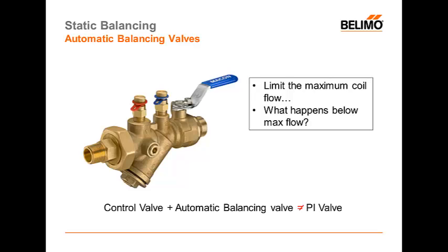One thing that's a very important point about automatic balancing valves. If you take an automatic balancing valve and you pipe it next to a standard pressure dependent control valve, it's not the same behavior as a pressure independent valve. That is a common misunderstanding in the industry.